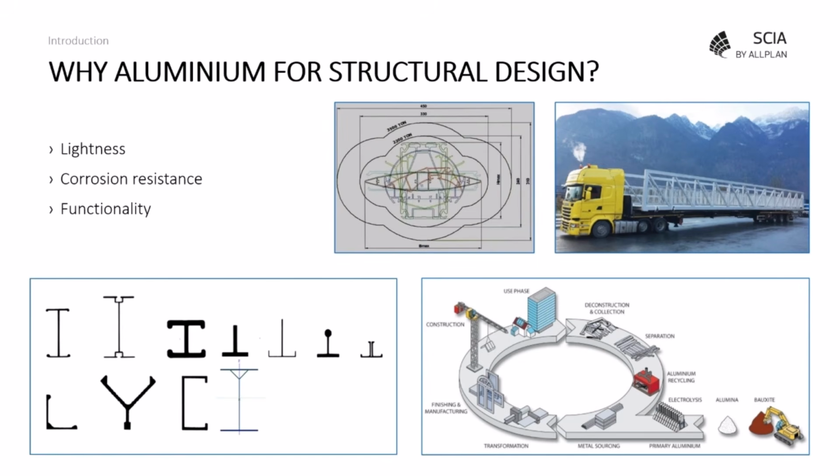For example, instead of using a regular I section, you can add some stiffeners, lips, or bulbs to strengthen the cross-section or to reduce local buckling effects on the location where it's needed.